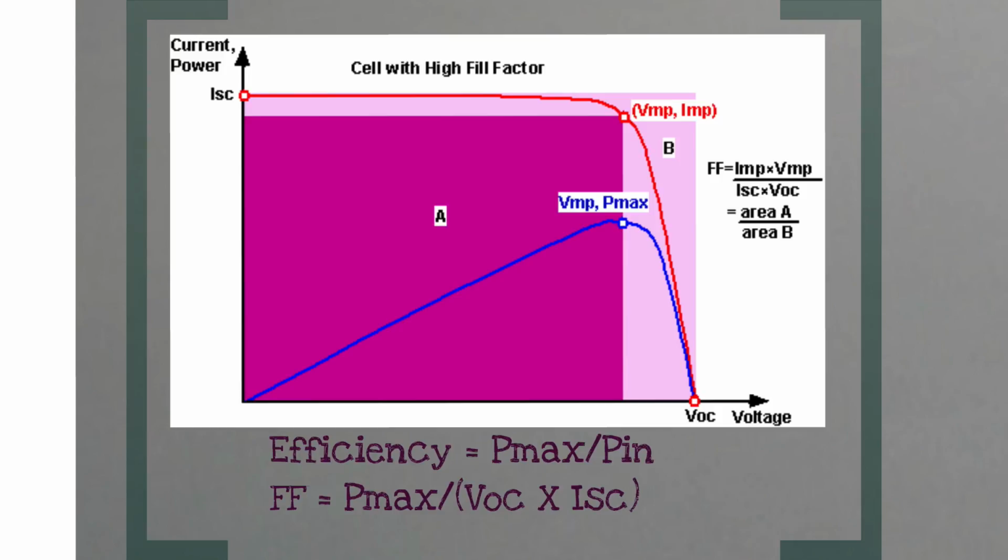Of course, if you take the current and multiply with the voltage, you can plot the power. So this is power versus voltage, and you'll see something which looks like that, which shows a peak value. This is the maximum power you can get out of the system, and it also tells you where you want to operate the solar cell. That corresponds to the amount of current that you really want to get out. You can do this by balancing the load, as some of you who are electrical engineers have probably done in the past. But for us, it's not so important from an optics point of view, just be aware that this is what happens.